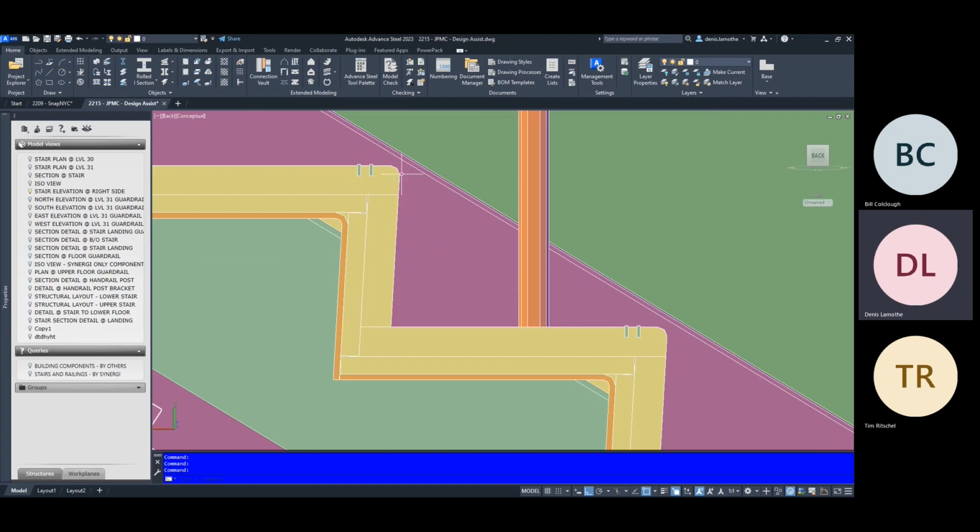If it's precast, you may want to go something a little smaller, maybe 1/2 inch is probably a good number to use, and the architect can review that after the fact during the drawing submittal process. If they agree with it, they'll okay it, and if not, they'll let you know what they want to change to. So yeah, nosings need to be radiused.